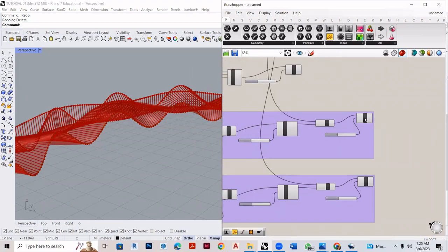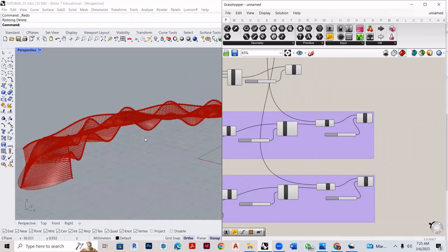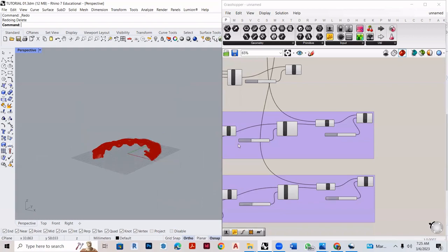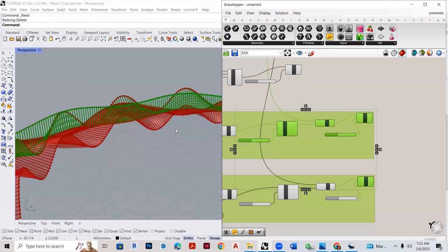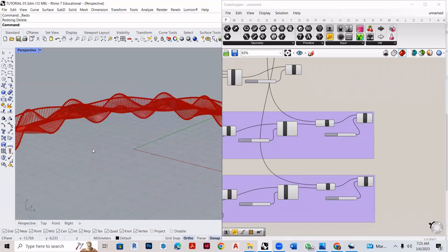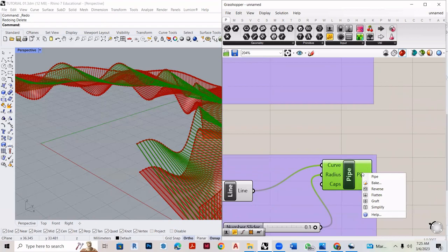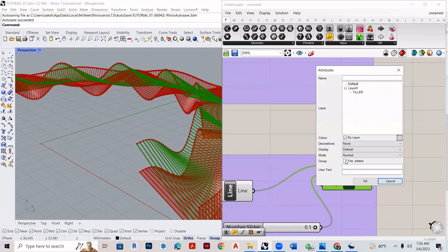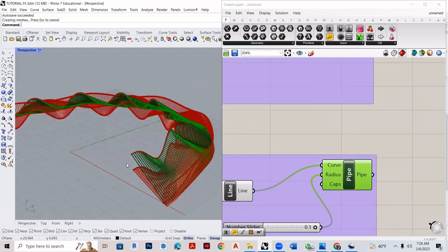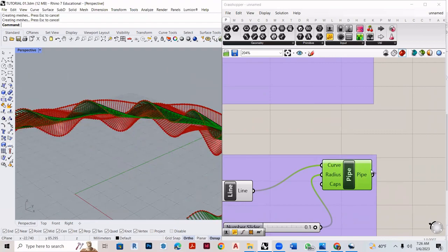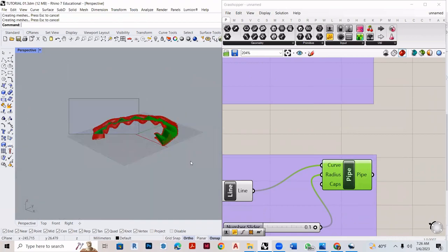Now, you need to render all of these on Rhino. If you select your script here, you would be seeing what all objects have been selected on Rhino, but these are not in Rhino currently. They are just a viewing interface. So in order to get your design on Rhino, what you've got to do is right click on the component and bake it. You just simply select group, yes please, and click OK. Once you do that, you would see that the component has been baked.